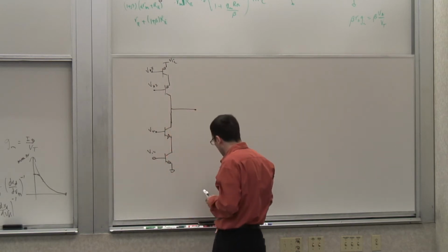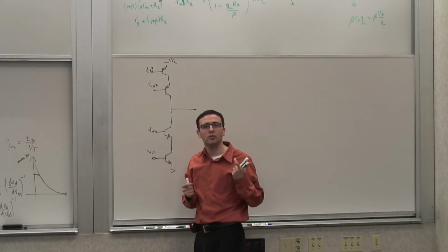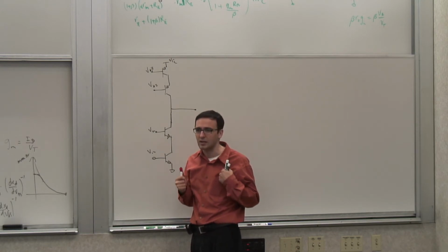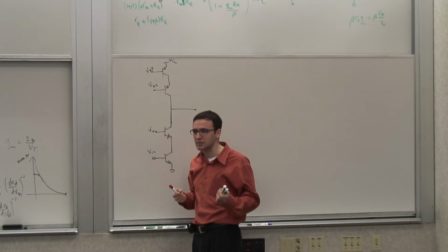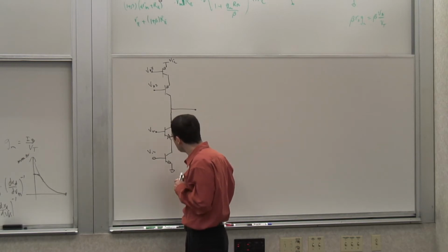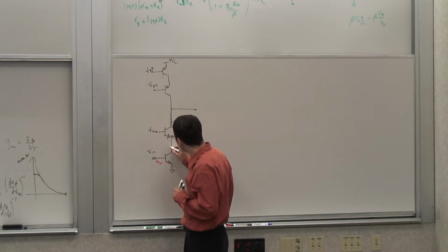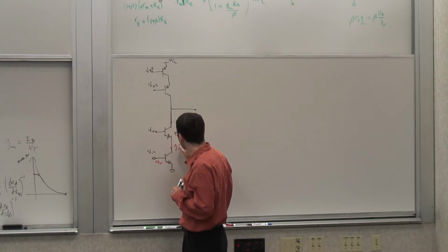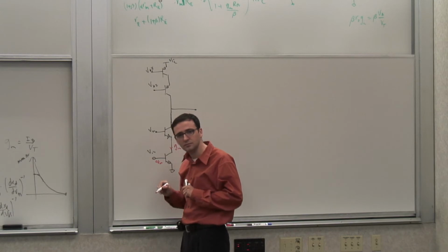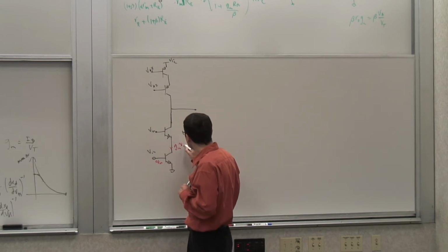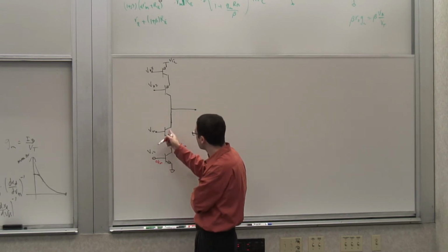Now, if you look at the gain, there are two components that result in the gain, right? There are two things necessary for gain: the drive and an impedance. So the drive here is, if this voltage is VN, this current is gm VN. And now you say, well, wait a second. Why do you say all of this current goes into this guy?